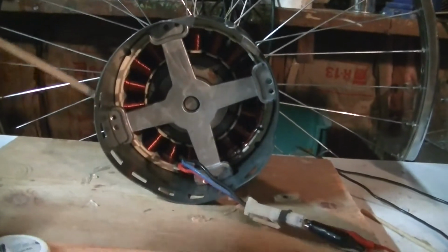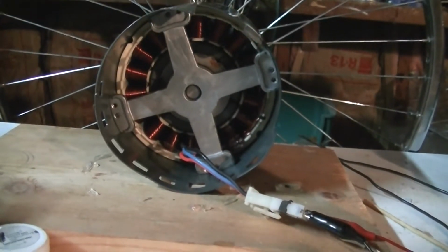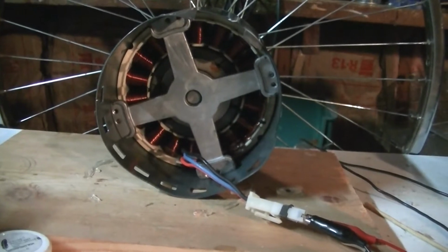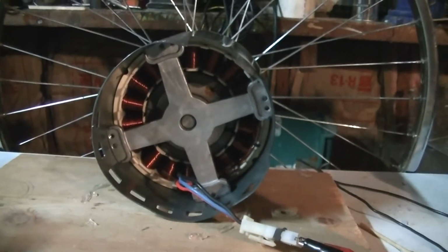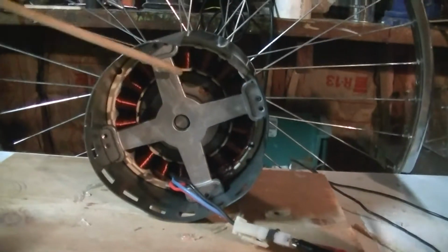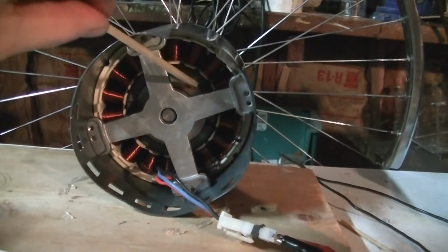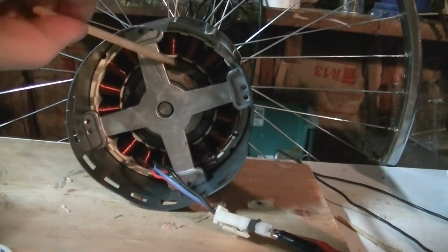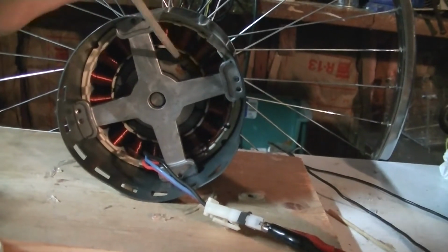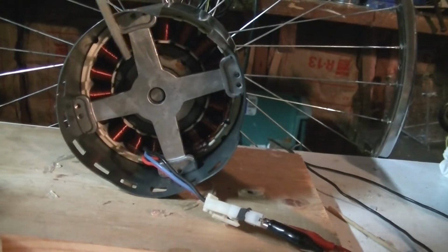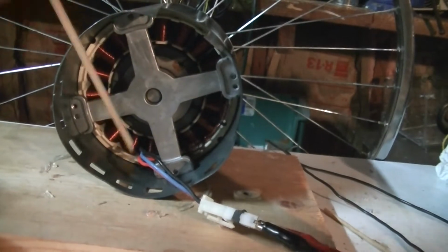And the gauge wire looks to be about 18 AWG. It might be larger than that. I'm not quite sure. I can't be solid on it. That's just a guesstimation. But figured I would do that. Three phases. Oh, and it has ceramic magnets that are diametrically opposed, so they go along the radius of the actual cylinder. They go north south per each magnet, and there's 4 magnets, so that makes 4 norths and 4 souths, 8 magnet positions altogether.